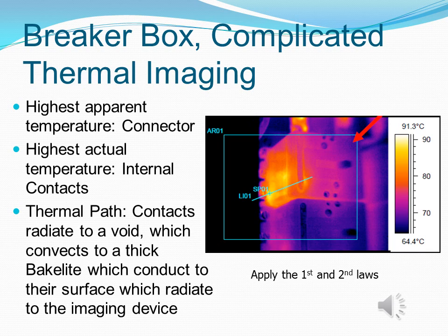Remember, the zeroth law saves us here as thermographers, but destroys the contact slowly, because the hot contacts seek to equalize within the small air void to both the bakelite on the outside, but it's draining out through there. It's seeking to equalize it also to the contacts, which are actually giving off the heat, but some of that heat goes back to that contact. It's convecting, right? So the heat is in both directions. The air void with the contacts and the bakelite, it's trying to seek that equilibrium. So that's the zeroth law.